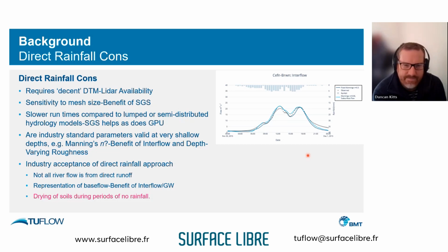Yeah, especially because when we are working on a big drainage basin, it's not too important. But when we are doing direct rainfall in urban areas with a smaller cell size, sometimes it could have an impact to take only one infiltration parameter at the centroid of the cell, or to be able to average different kinds of infiltration parameters, etc.